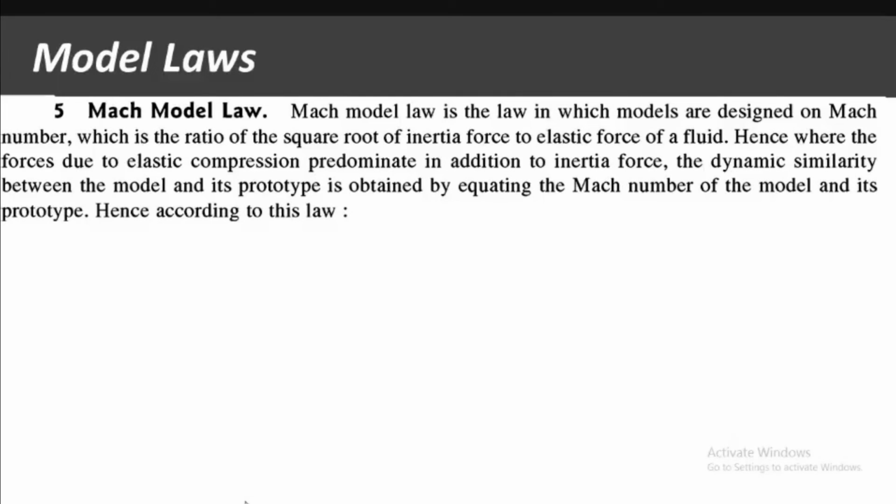Mach number is nothing but the ratio of the square root of inertia force to elastic force, and this elastic force plays an important role in compressible flow. In case of incompressible flow or liquids, it does not play an important role. Therefore, Mach model law is applicable where gaseous flows are taking place.